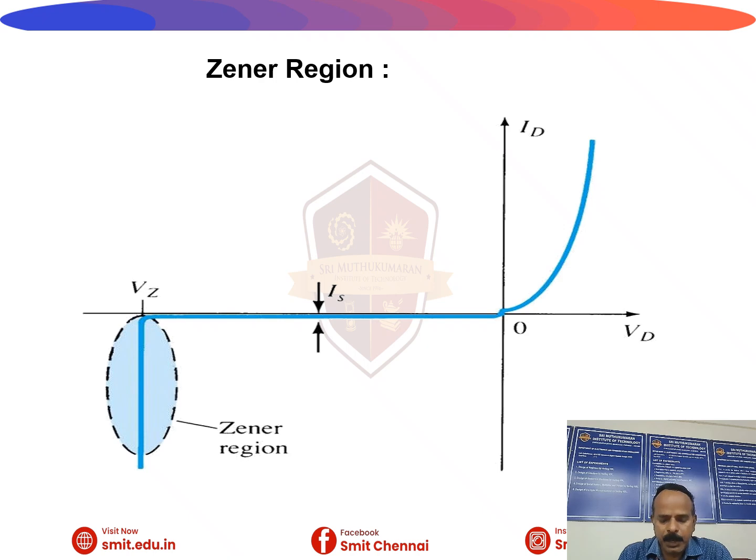The Zener region and the reverse characteristics. In the reverse bias, a small reverse saturation current initially flows due to minority carriers. This current is almost independent of the applied voltage and remains very small in nature. As the reverse voltage is increased further and reaches the breakdown voltage, the junction breaks down and the reverse current increases abruptly. If the current is not limited, the large current can destroy an ordinary diode. However, the Zener diode is specifically designed to withstand this breakdown region safely.